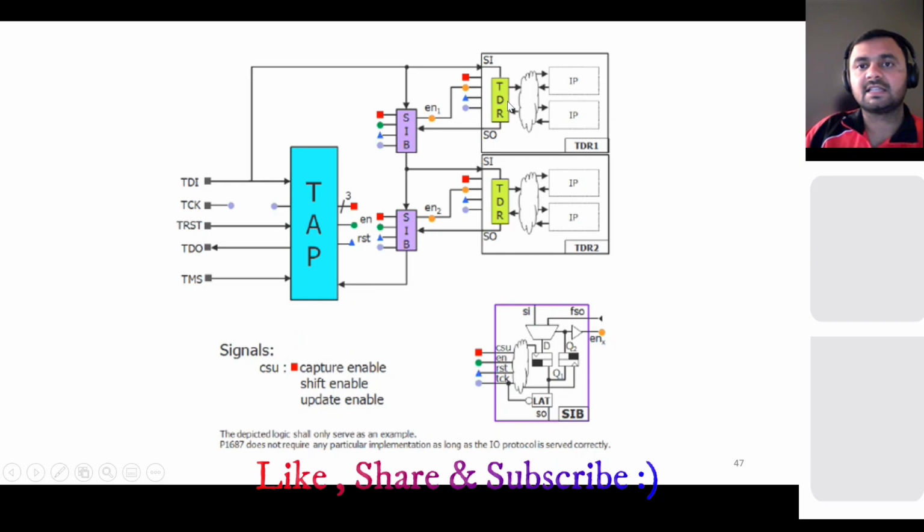You can see this TDR is placed in front of the block, and through TDI you can shift in the data and shift out, and using the SIB you can again route it to the TDO. Through TDO you can measure it. So using this 1687 or IJTAG, it's very easy to test any of the blocks. You have very easy control or access to any of the blocks using these TDRs and SIBs.